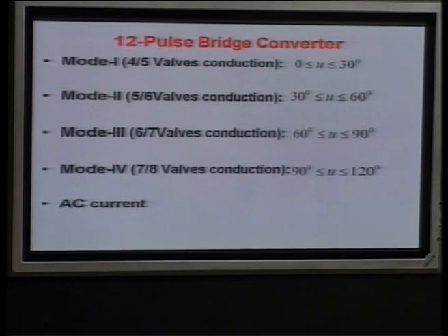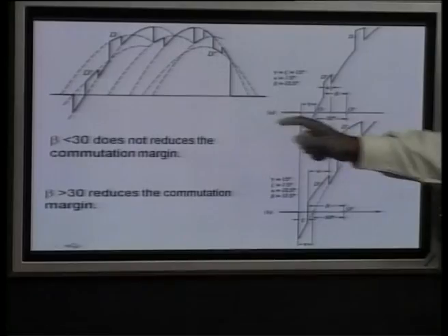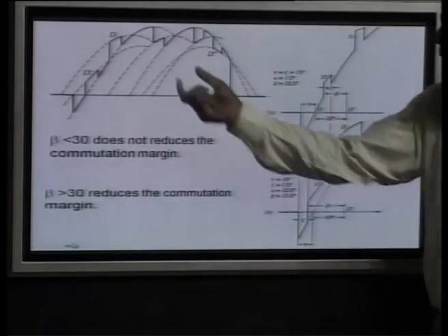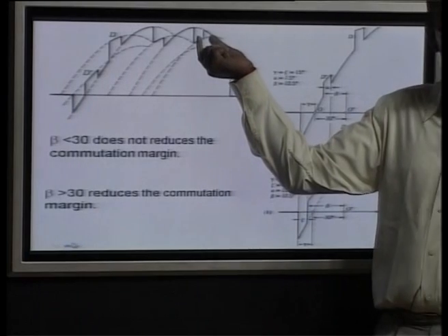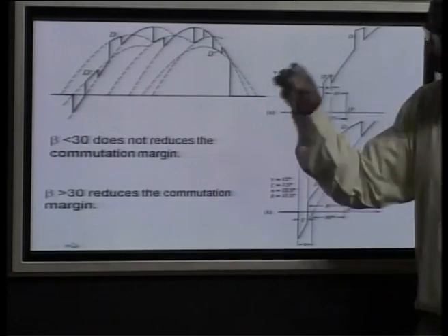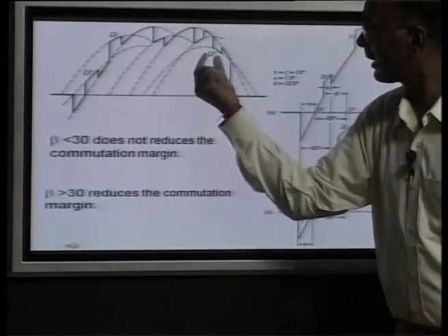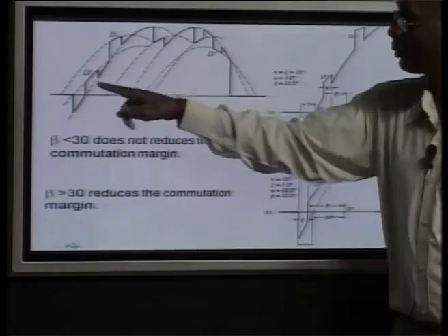Moreover, if you see the current, which I already explained to you, due to this conduction pattern we are having extra dents here, arising for the lower one. You see one dent was coming from the top, and this was another dip here. It was arising if the 6 pulses were there. Now, due to the conduction of the other bridge, we are getting one dent here, another here. I can say D prime or D double prime are there.